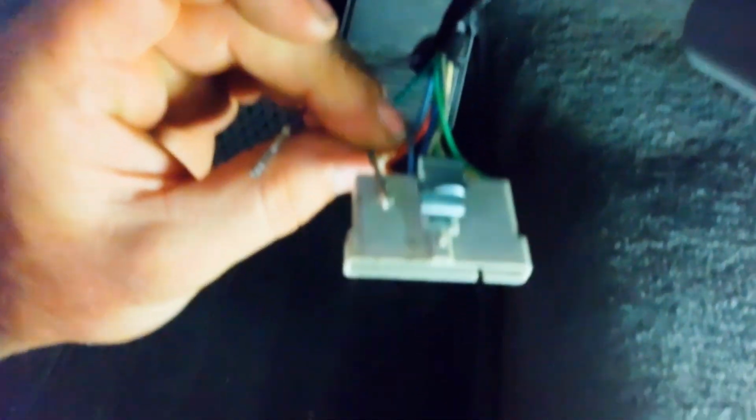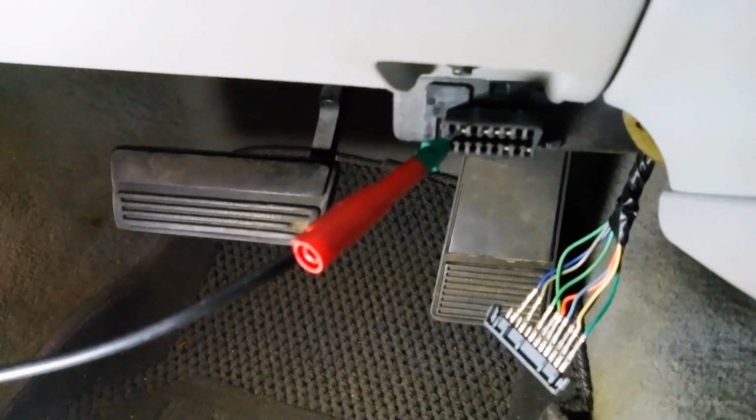I've got a little T-pin. I'm just going to put it in here. There's a little retainer. Pry away from the connector and pull each pin out individually. I'm going to repeat that until I get all these out. We're going to plug them all back into this comb, and we're going to get a network signal, see what it looks like. This way we can remove individual modules from the network and see if we have a bad network connection, if it makes any difference.